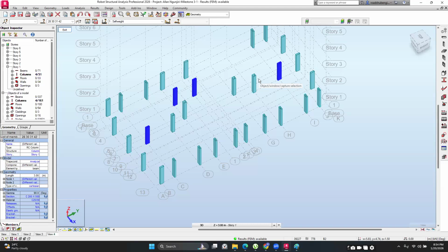Even on site, it's going to be a lot of work and it's going to bring about confusion. So whenever you're designing, you want to make it relatively easy for everyone. For yourself, as you're going to be doing the detailing work, for your approval purposes as well, and also for the guys on site. So that's why we always group the columns together. You can see that these columns here have the same cross section and are within almost the same region in the structure, so you expect them to have similar loads or similar design.